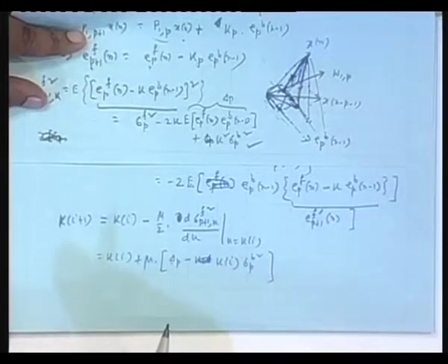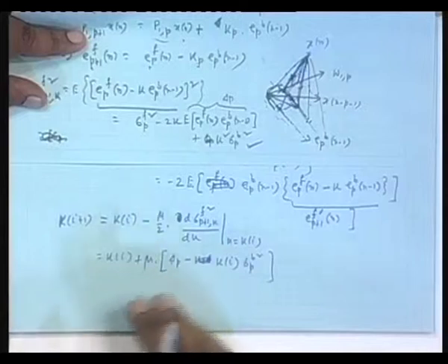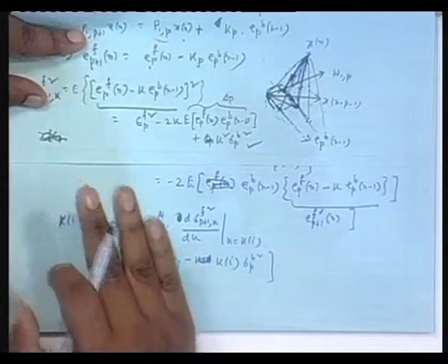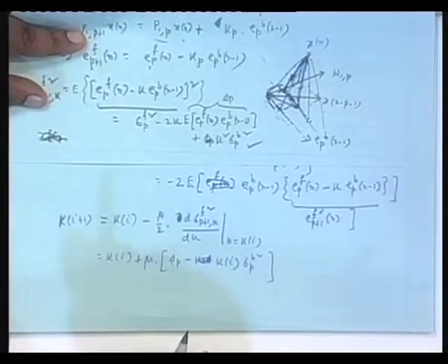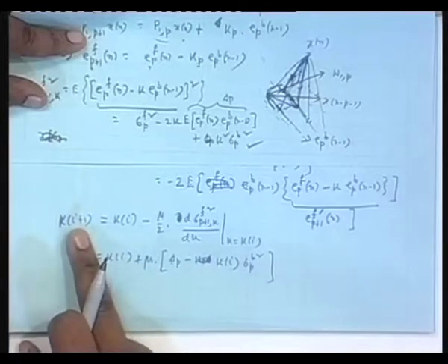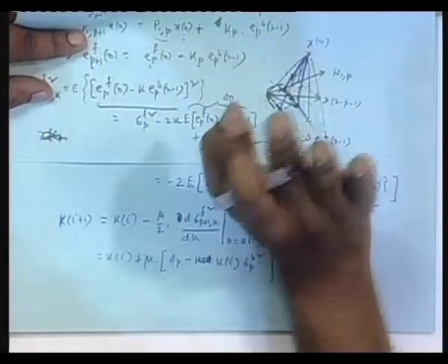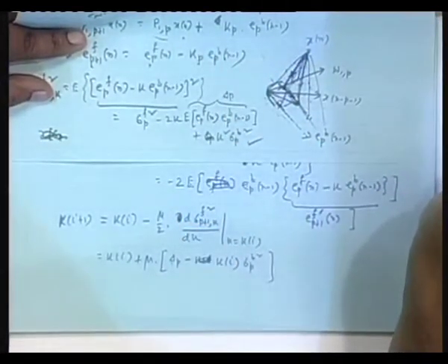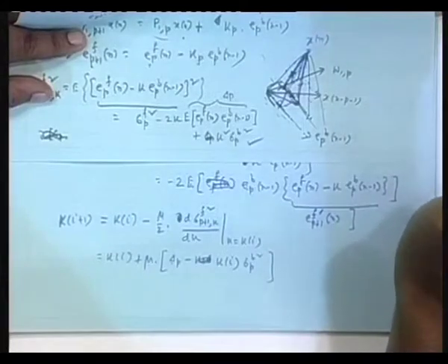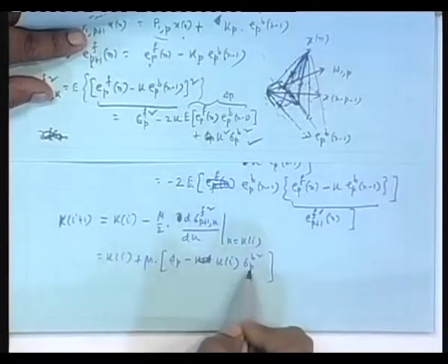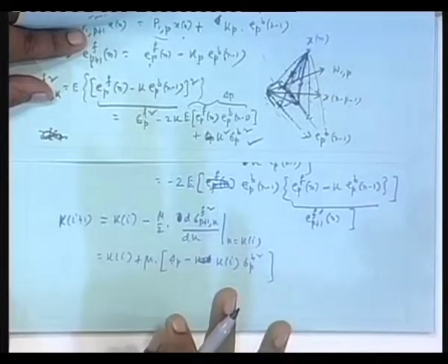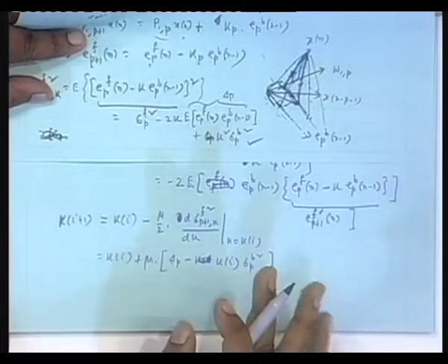Now, suppose I want to move from here to LMS. Again, I will see the procedure is very similar, absolutely similar. The first thing was to replace i by time index n, as though I am carrying out the iteration by looking at my watch, in time. Fine. You remember that is how we went to do LMS from steepest descent. i was replaced by time index n, and these correlations will be replaced by some wild estimates. Same thing.